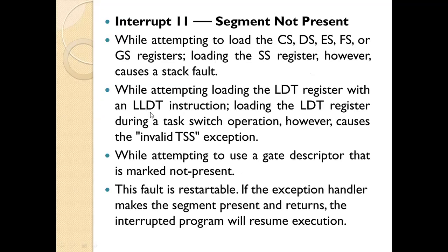Interrupt 11, segment not present. It occurs while attempting to load the code segment, data segment, extra segment, FS or GS register. Loading the SS register, however, causes a stack fault. Loading the LDT register with an LLDT instruction, or during a task switch operation, however, causes an invalid TSS exception.